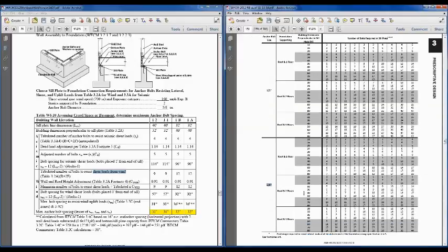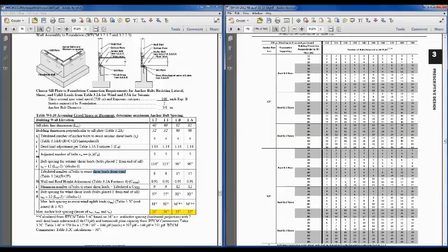So a roof and 2 floors, working our way across to the 160. Shows that 9 bolts are required. And again, footnotes with those tables could be used, and then you calculate a 57-inch spacing. Well, so we've looked at our shear loads for wind, we've looked at our shear loads for seismic.